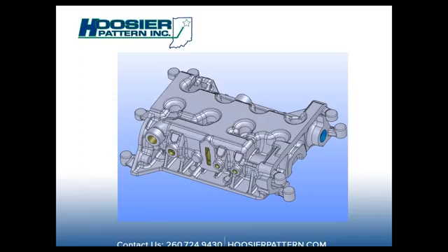In that regard, all you have to do is put a slab core under the drag if you wanted extra material. On the sides of the mold, you could backfill it with green sand or air set. And you don't need to print a cope just to get riser height or pour height out of this. You can add that with your molded sand as well and just print what you need.